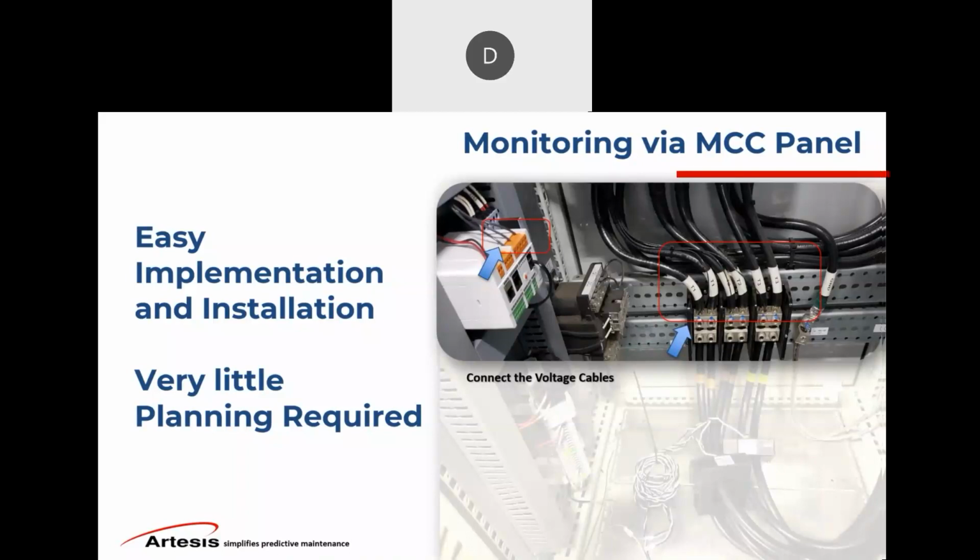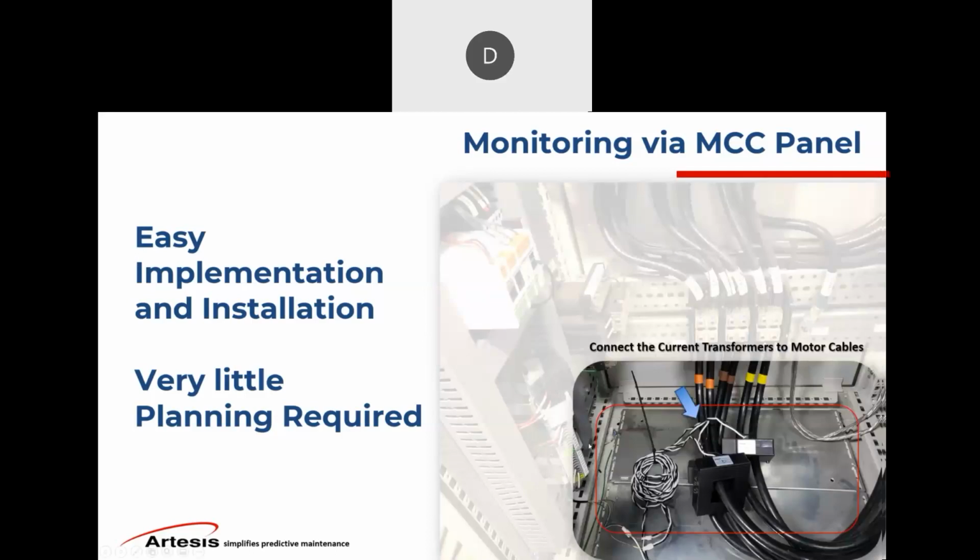So we just need to get the voltage, we need to get the current, and then the data out, right? The arrow is pointing towards the orange terminal block here, the three voltage leads, it's just 12 or 14 gauge wire. So again, right off the shelf, very easy to install. Then we need the current. Down here, we provide you with the correctly sized CTs. You don't have to source those. We have them for you.